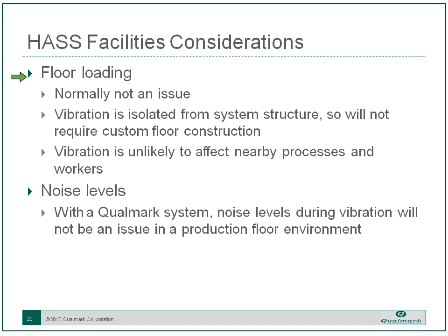Fortunately, with repetitive shock machines, that's not an issue. You just have to be able to support the weight of the chamber. The vibration is isolated from the system structure. The whole vibration table is mounted on springs. So there isn't that equivalent downward force into the floor that you have with electrodynamic shakers. And no custom floor construction is necessary.